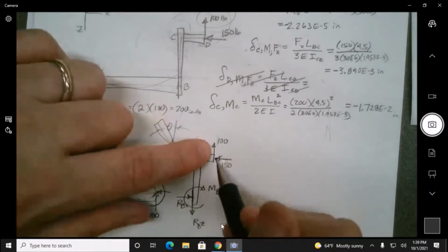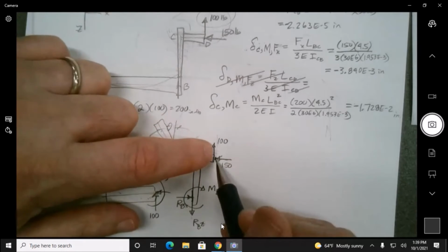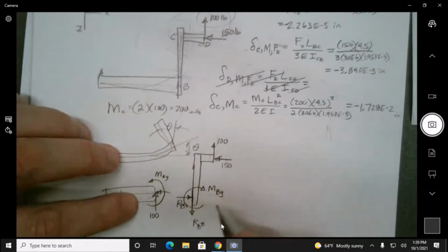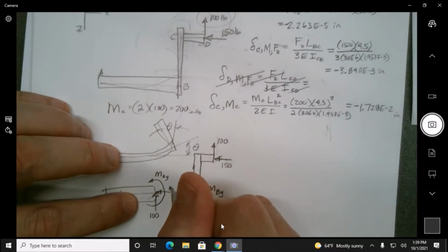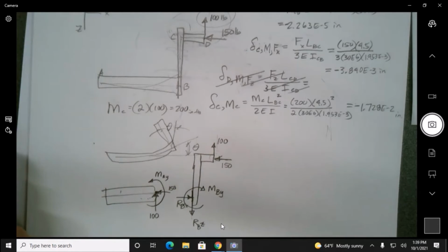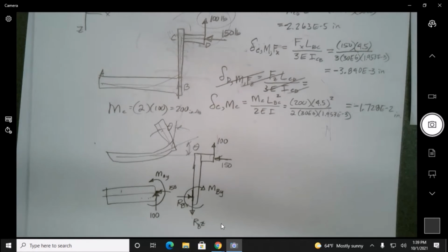What we've essentially done is transfer these loads from this point over to this point, and in doing so, we created a moment. That's another method of doing load analysis. We usually think of those as couples. In statics, sometimes there's a section on couples, and I don't know if we ever got across. A reason why we're doing that is that another way of analyzing a specific spot is to take the load at its actual location, transfer it over, and in the process create a couple. So that's possible.